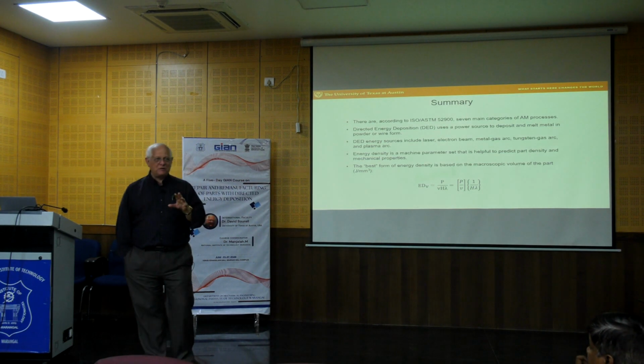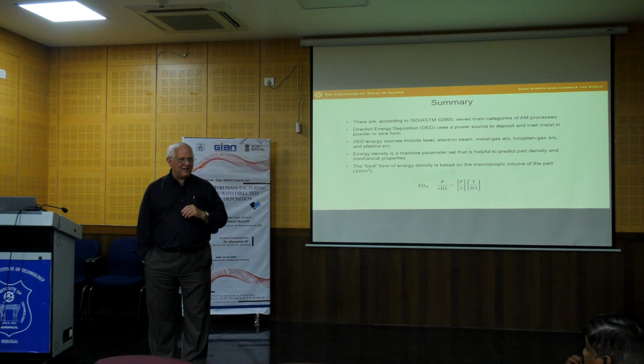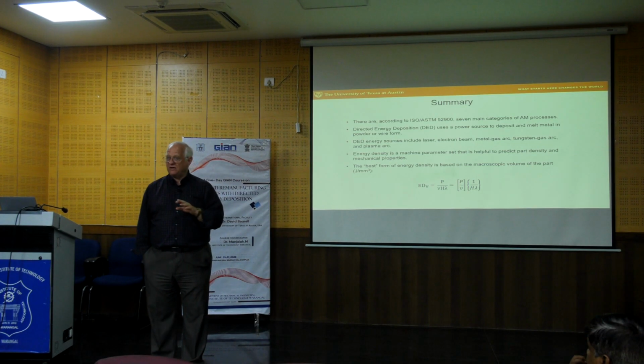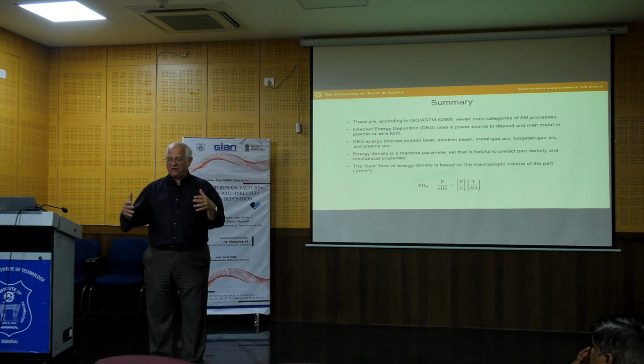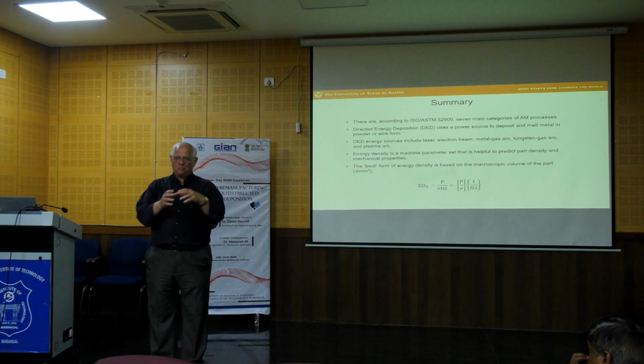My own personal opinion is they sort of, I don't know if they did a business deal or if they just stole the technology, but Neil Hopkinson in the UK had this technology that he called selective high-speed sintering, where he put down basically a coupling binder like carbon black, which can happen very quickly in the layer, and then he simply immersed it with an IR heat source, where the carbon black would get really hot, but where there was no carbon black, the material would stay relatively cool.